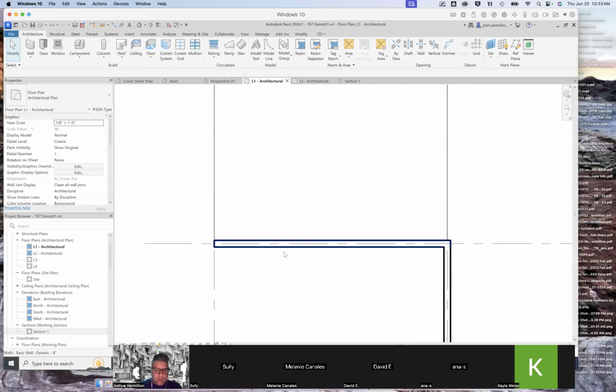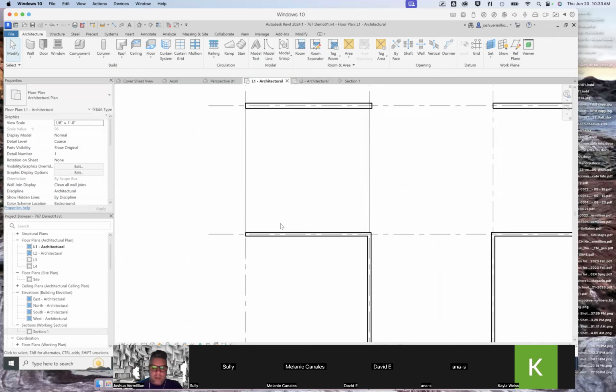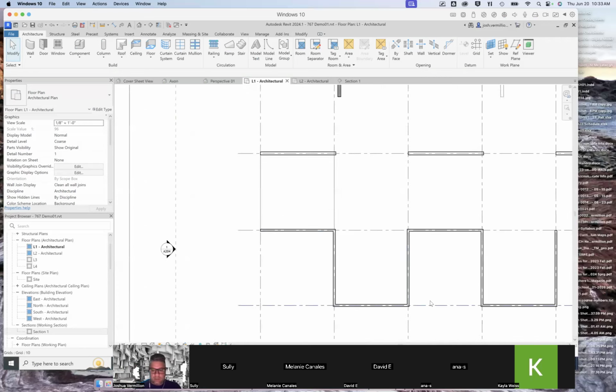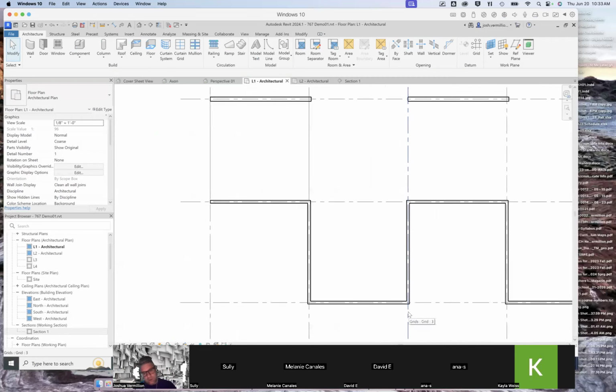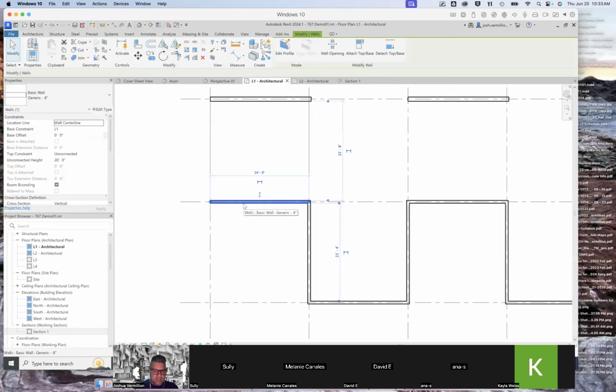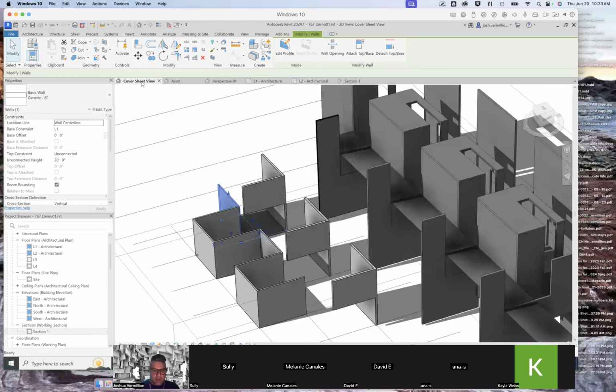And so let's just turn it back to wall center line. So anyway, what you can do is you can begin to draw, but you can also specify, are you drawing the inside of the wall, the outside of the wall, or the center of the wall, or the center of the core, wall core, whatever. All right. So just so you know that there's a granularity there. Sometimes if you accidentally toggle one of these things and you don't realize it, then suddenly it doesn't react the way you'd expect it to. But that's probably the first place I would look: its properties. Select the object, look at its properties, and see what's going on.